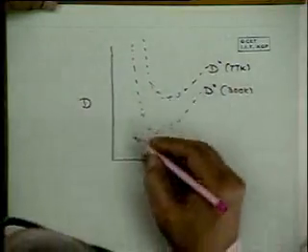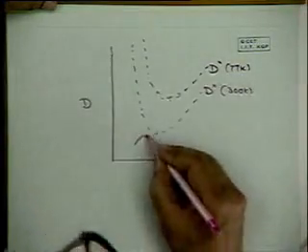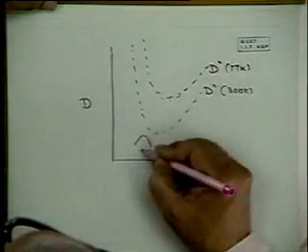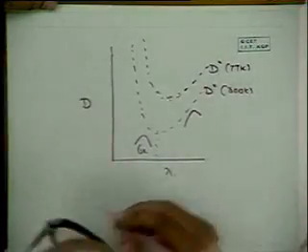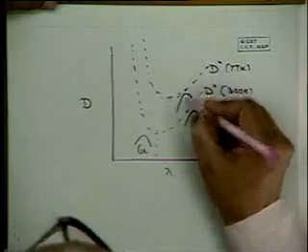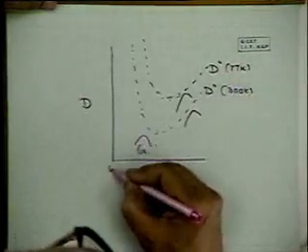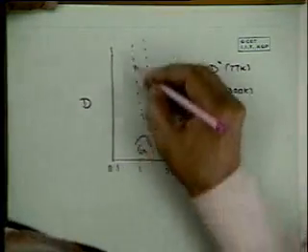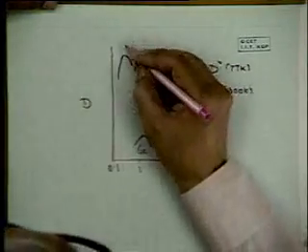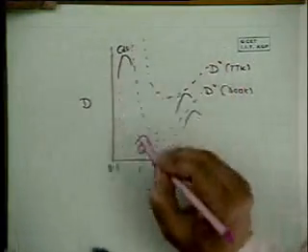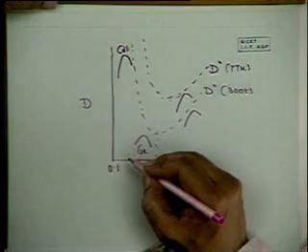For example, a germanium detector will occupy a detectivity curve around that region. Indium antimonide detectors will be there. At low temperature, one can have detectivities of there. The cadmium sulfide one that I mentioned, say this is 0.1, this is 1 micron. Cadmium sulfide detector occupies a position here, whereas the mercury cadmium telluride detector occupies at 10 micron.